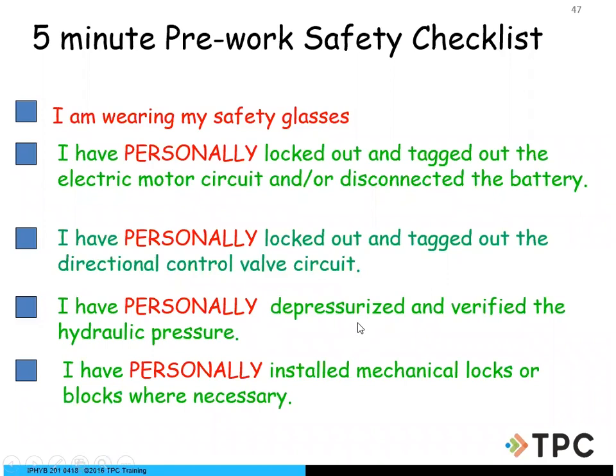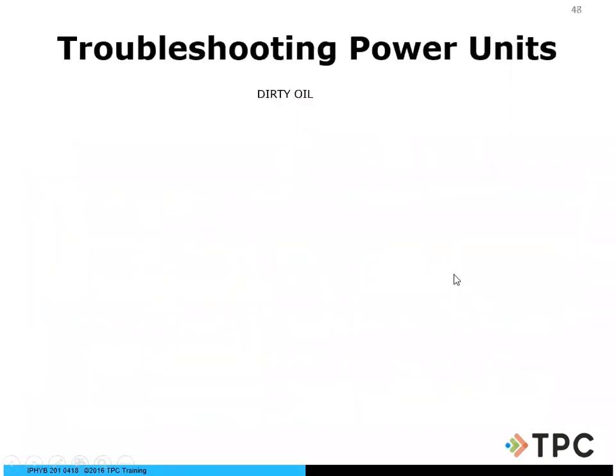So depressurize the system, verify the hydraulic pressure is 0 if we're going to work on it, right? And then install mechanical locks or blocks where necessary. Absolutely critically important for your safety and everyone else's safety. So when you're working on these systems, mechanical, hydraulic, electrical, make sure there are no forces on there.